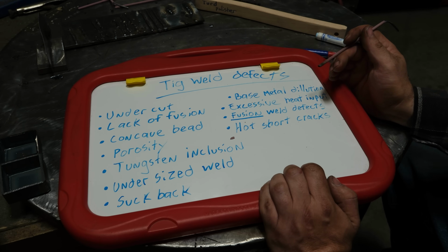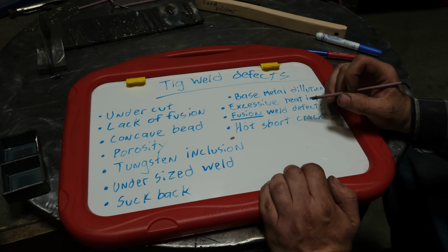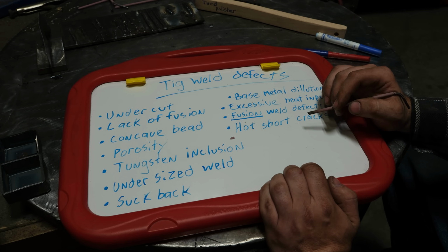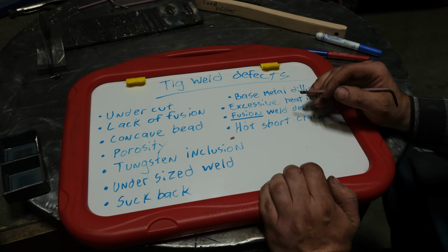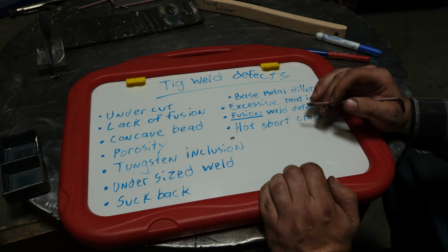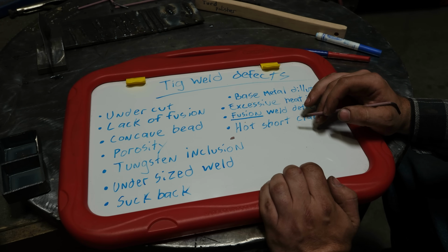The material will be known as hot short sensitive. So aluminum is hot short sensitive. And what that means is you do not want to weld those types of materials where you are fast on the gas of your amperage pedal, your foot pedal with TIG, to where you're hammering on the heat, moving fast, and then just tapering off in an instant.